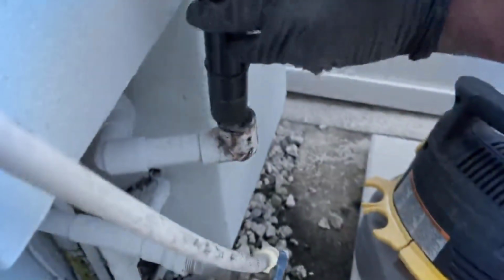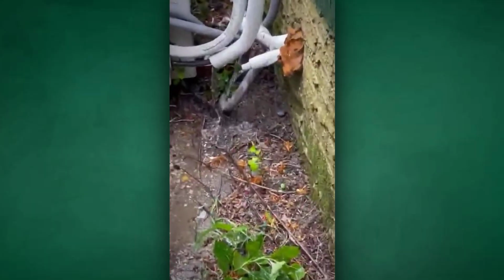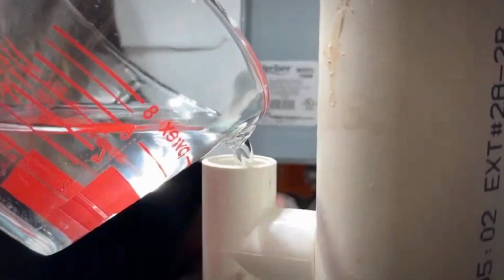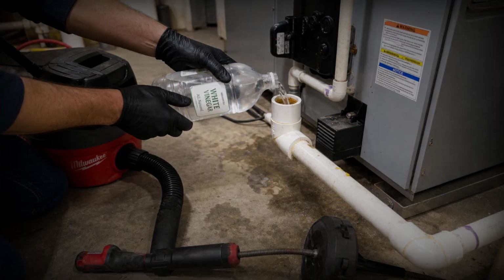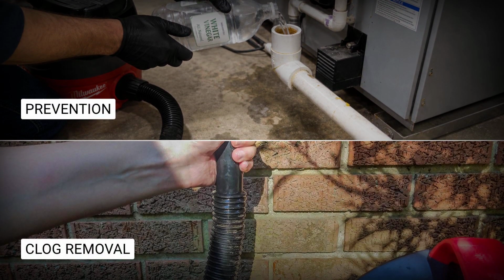The important word is remove. A physical plug requires a clearing method that physically restores the path. That order matters. The vacuum, hose, or snake addresses the obstruction first. Cleaner and water follow after the path has been physically cleared. A tutorial that begins and ends with pouring skips the part both manufacturers use for an actual blockage.